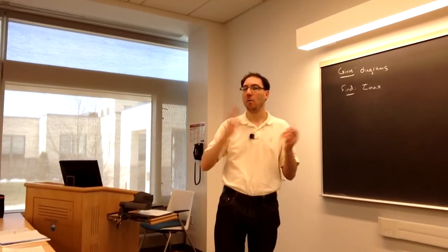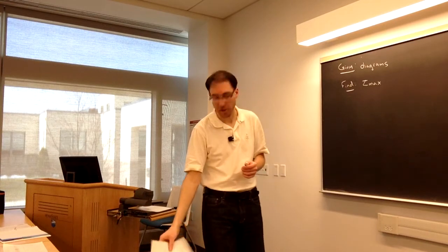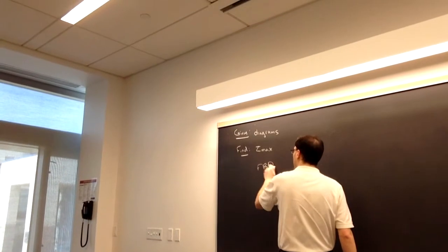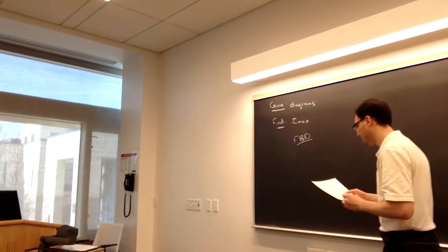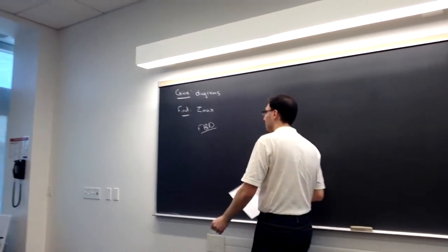So the first step, right, where is V the maximum? Because if we maximize V, we're then also going to be maximizing tau in the VQ over IB calculation. So where we want to start here is with our VM diagram, since we don't know up front where along the length V is going to be the maximum.